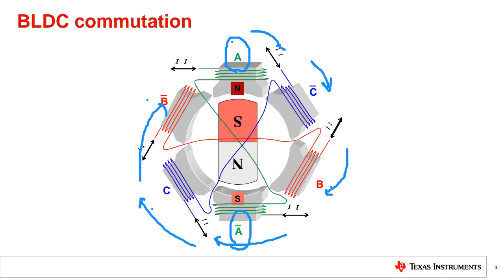Why are we using DC motors in home appliances generally? Because they are cheap. However, in washing machines, dishwashers, and in the last few days, all the advertisements about Dyson, they use brushless DC motors because they are silent, because they have high torque productivity capability, high efficiency, etc. In the work, efficiency is very important, so all companies convert their DC motors to brushless DC motors.